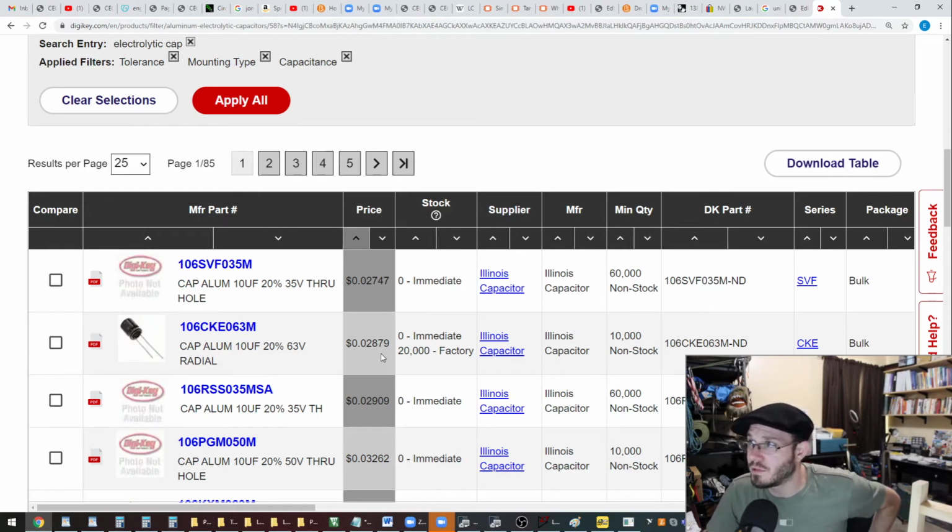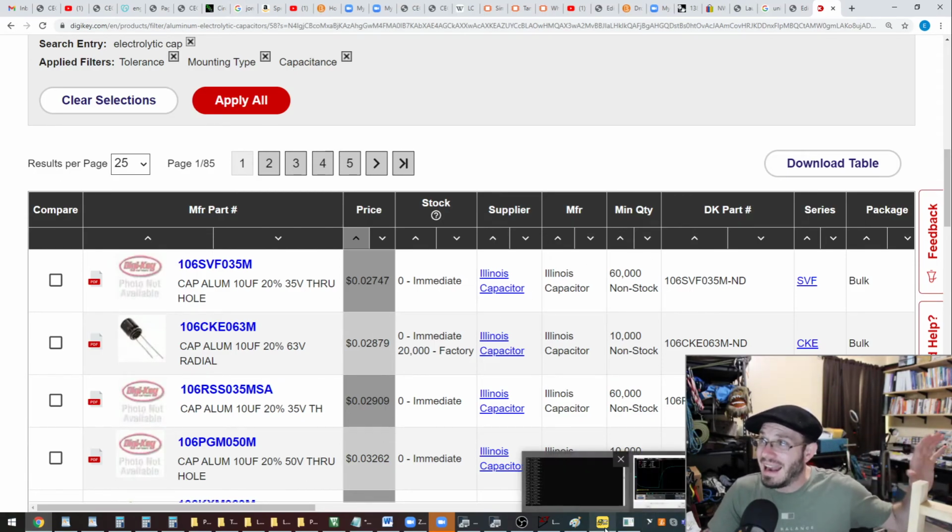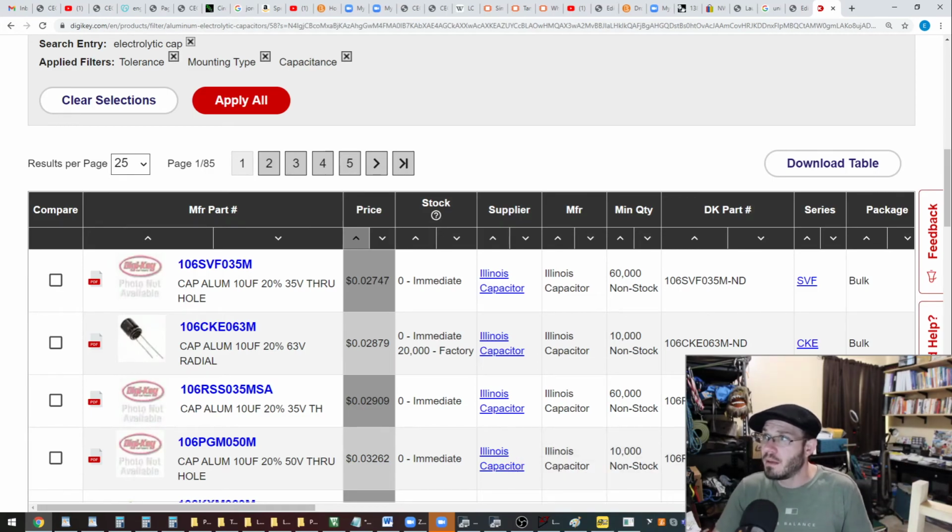I may have like 20 of these in a design. There is no way that I can afford to make a consumer product charging 40 cents a cap just to have plus minus 10%, which is still terrible tolerance. Okay, so this is why I'm not concerned about being that accurate on the oscilloscope, because that voltage measurement is really at the mercy of the tolerance of my cap.